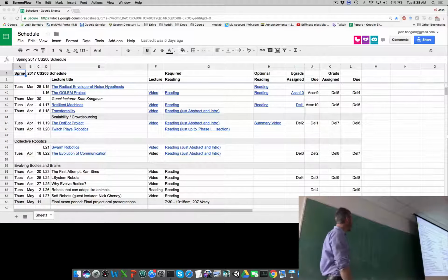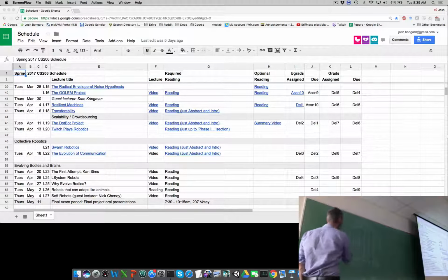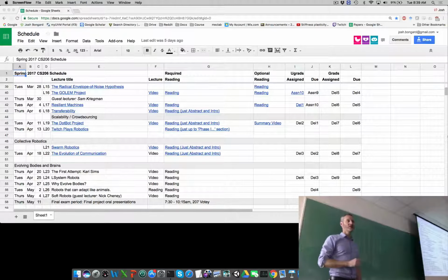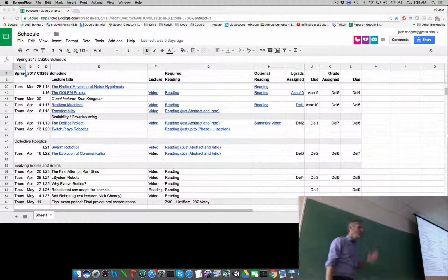sensors in my robot. Let's say I've got the 4 touch sensors, and let's assume that I'm also going to have a ray sensor, which I'll just represent with Y. And you remember that the ray sensor actually has 4 components associated with it. The position sensor has 3, the X values, the Y values, and the Z values. The ray sensor has distance information. It'll give you back the length of the ray emitted by the ray sensor. And it will also give you back a red component, green component, and blue component of whatever that ray sensor hits, the color of the object that the ray sensor hits.